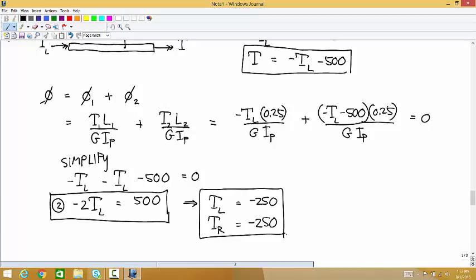Yep. So is there a proportionality with that? Like if you move that T away? Yeah, the closer, the one that load is closer to takes more of the load. Would that be linear, like at 0.25, then we'd expect negative 125, and then 375? Yeah, and you can see where it comes in. It just comes in with the lengths of those members, the length of each individual cut or each individual piece in the sum.